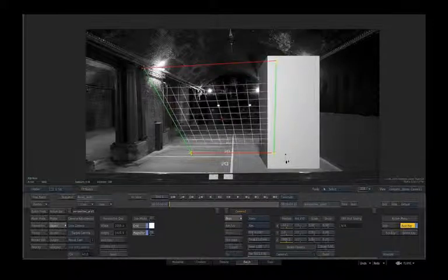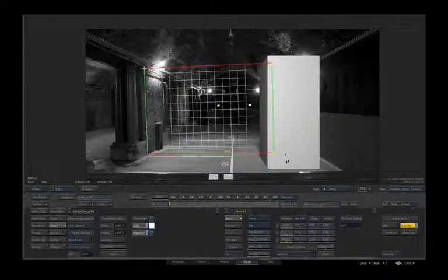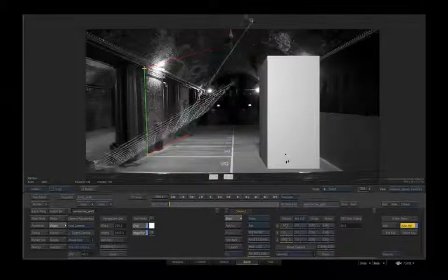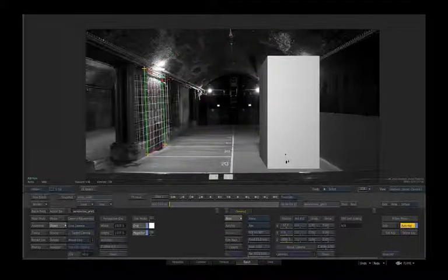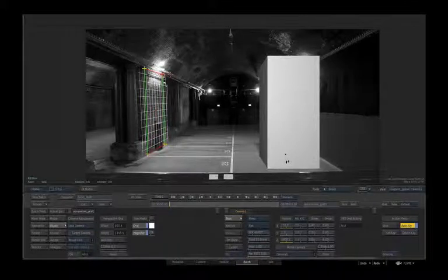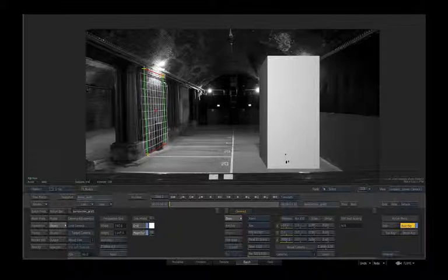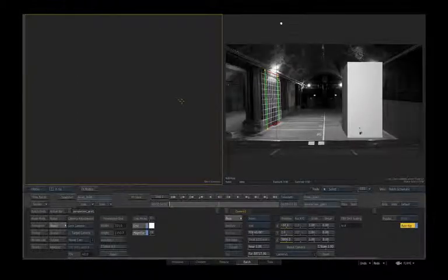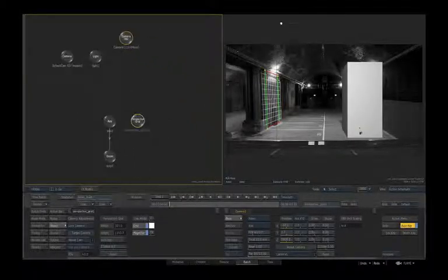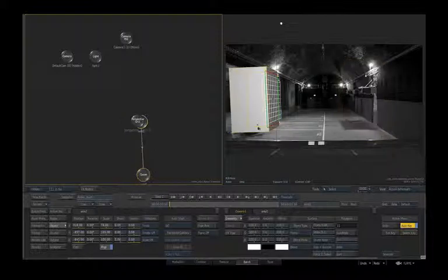In this case we want to align to this wall, and it doesn't really matter even if you can't see all the points that you're working with, but if you can guess where they are in space, as I'm doing here, you can then start to judge exactly how things would come together. So by just carefully picking those points, we would then align our cube to this. So let's just come in here and hang these guys off each other. So you can see how that will just snap right in,